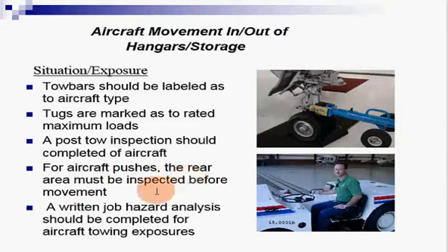For aircraft pushes, the rear area must be inspected before movement. If there is any hurdle or obstacle which can result in a fatal kind of injury to the aircraft or the personnel, you have to move that. A written job hazards analysis should be completed for aircraft towing exposure.